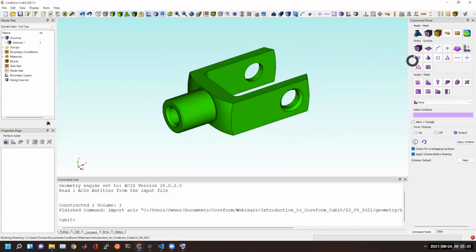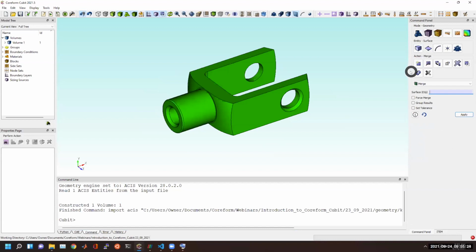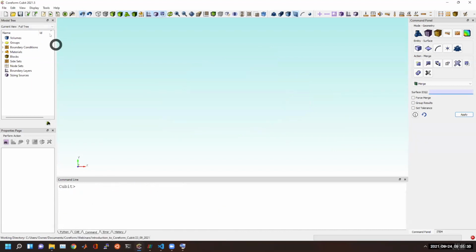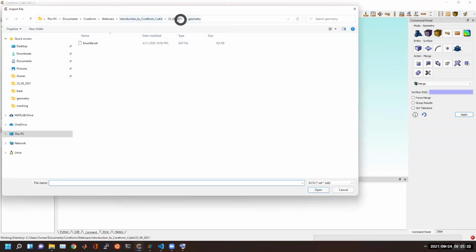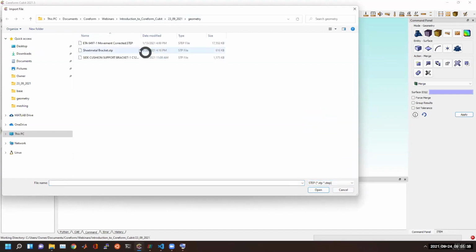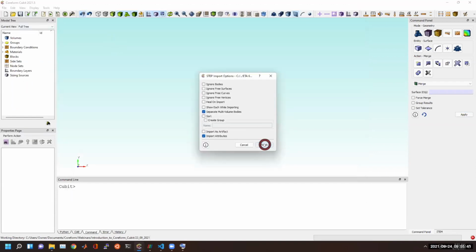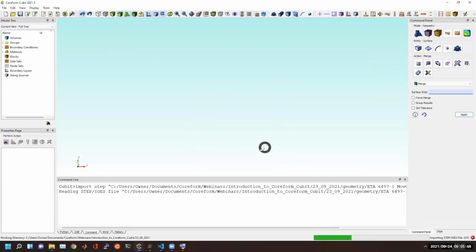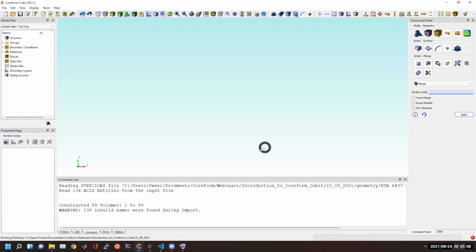So I think what you're asking is, say that we had, let's import this watch geometry that we had. I think what you're asking is, how do I propagate a TET mesh from one volume to another? Yeah, so here's a clarification from Ron: for an organic shape where the smaller details need finer meshes than the larger features, how to control that.